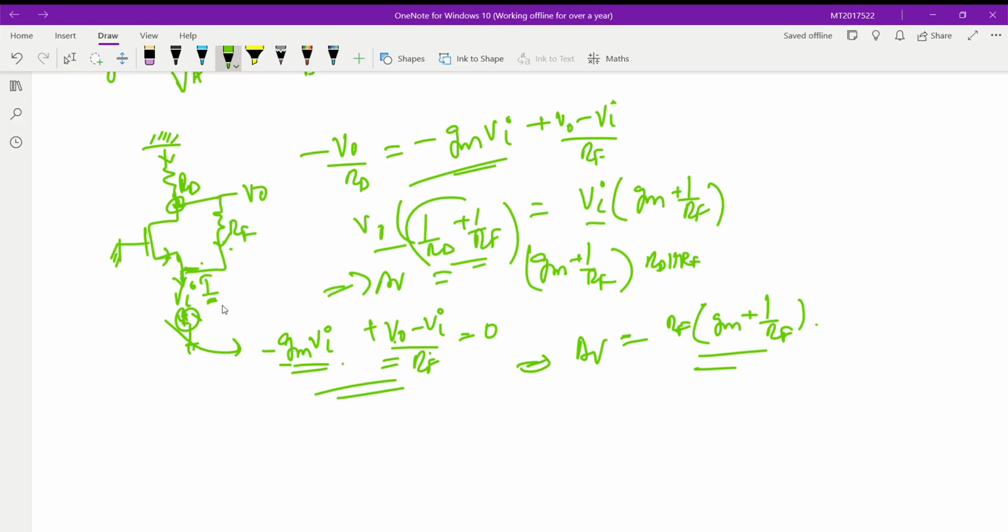So what does it mean when we ignore a current? It means that the impedance here is very high. So we are mainly looking at something like this. Suppose this R is very high, and we are putting a Vi here. At this node the potential will still get Vi, but the current will be zero. So when we are using this equation, we are inherently assuming this. That means there is no current going downward.